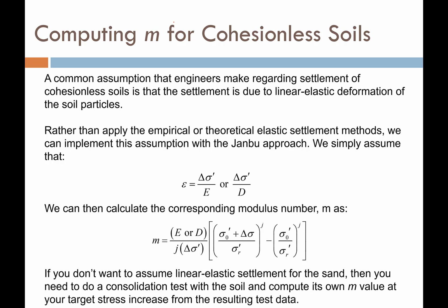Now, a common assumption that engineers make regarding settlement of cohesionless soils is that the settlement is due to linear elastic deformation, or elastic deformation of the soil particles. But rather than applying the empirical or theoretical elastic settlement methods that we learned in 341, we're just going to use the Janbu approach.